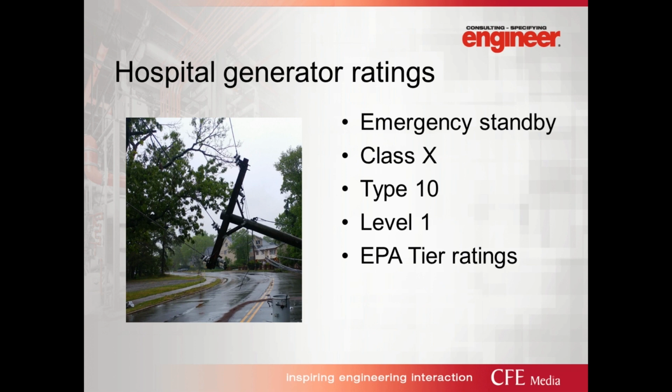Additional generator characteristics that the engineer must be familiar with for designing hospitals are the ratings that you find within NFPA 110, Chapter 4, which is specifically the class, the type, and the level. The class defines the minimum time in hours that the system is required to operate at its rated load without being refueled or recharged. Hospitals fall into Class X, which basically means you figure it out. NFPA designates Class X as the time required as determined by the code or the user.